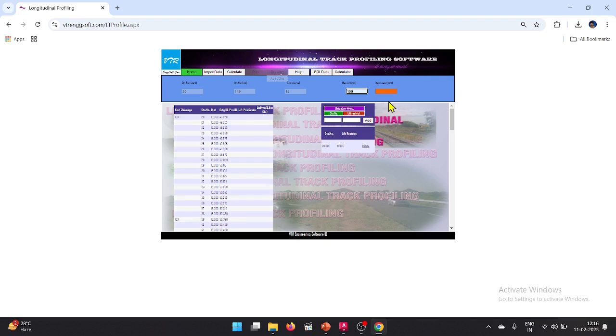When you are lifting the track, what will happen? Platform level will come down, the height will be reduced, and thereby it will infringe. Sometimes it will give more gap between the step and the platform. That will affect the passengers who are boarding the train. So that is why there also we will restrict. Like that, sir, many obligatory points will be coming across, and at those locations normally we will give 0 lift.